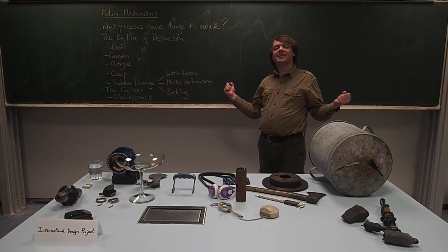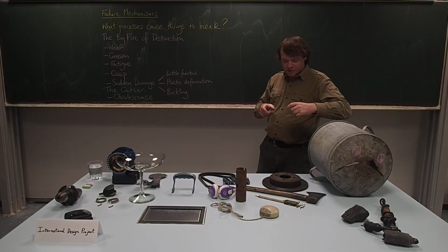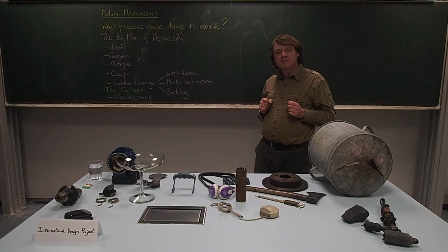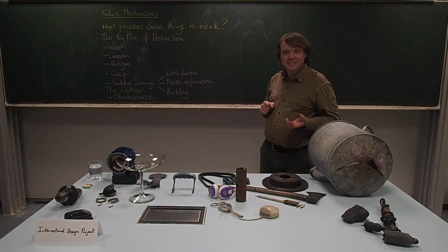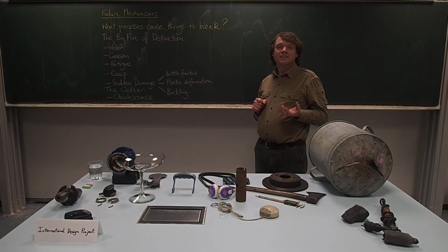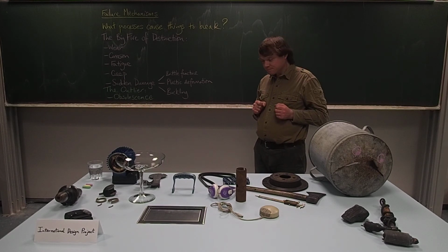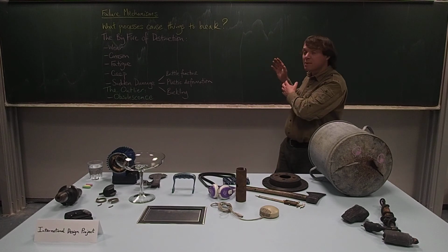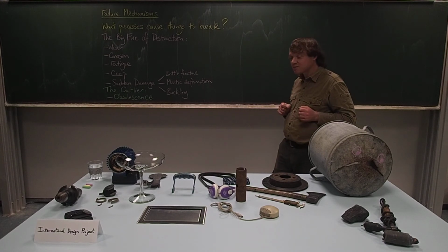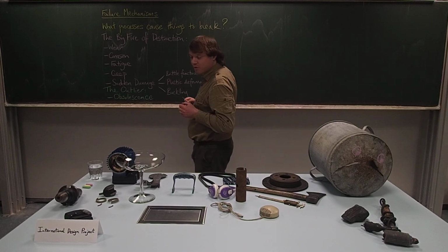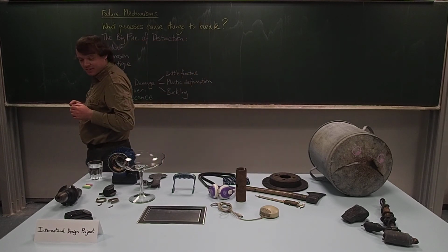Now, if someone takes out those deflector plates, which are just small pieces of sheet metal, then very slowly, over the course of years, the oil is lost, and then the pump fails by wear. Now, there are very many other failure mechanisms. These are the big five of destruction. I can give you one or two more examples here that you can think about.